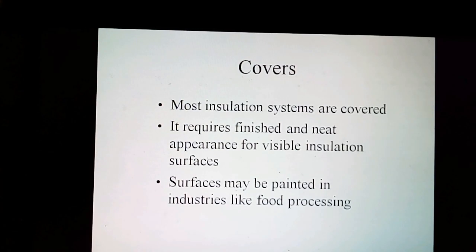Aesthetics. Most insulation systems in commercial construction are not generally visible. The common exceptions to this are found in equipment rooms where the heating equipment, cooling equipment, and the associated piping are visible to the personnel who work or otherwise must access these areas. It is common practice to require a finish and neat appearance for insulation surfaces that are visible within the building envelope. These surfaces may also be painted or covered for a more acceptable appearance in the case of hospitals, schools, supermarkets, restaurants, and even in industrial facilities for food processing and computer component manufacturing where visible to the occupants.